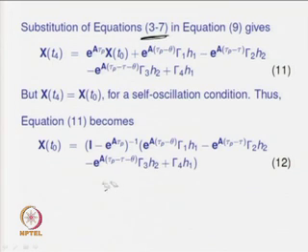So, when equations 3 to 7 are substituted in equation number 9, we get x(t4) is equal to e^(aτp) x(t0) plus e^(a(τp − θ)) γ1 h1 minus e^(a(τp − τ)) γ2 h2 minus e^(a(τp − τ − θ)) γ3 h2 plus γ4 h1. So, all the gamma values are present here, as well as all the time spans have been considered to get this solution x(t4). So, the value of the state at time t equal to t4 can be obtained using this.